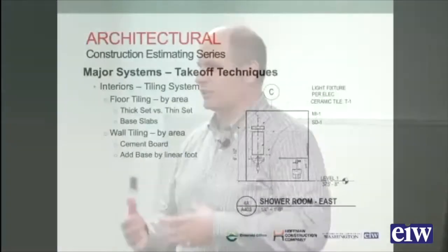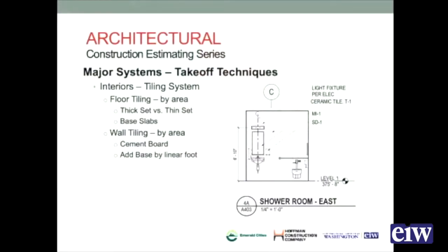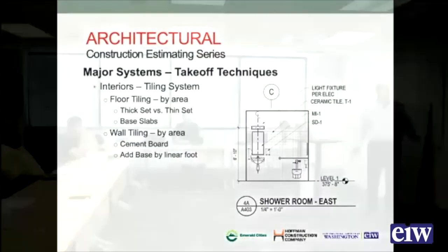Moving on, then we'll look at tiling first. And I separate tiling out from wall finishes and floor finishes because it's both. So tiling is typically looked at a little bit differently because it's a floor system and it's a wall system and it's a base system. And it's the same subcontractor who's going to be doing all of it. So, things about tiling: again, the wall tile and your floor tile are going to be by area. Your base is going to be a lineal footage.